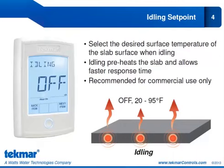In the set temp menu, you will enter the desired surface temperature of the slab when idling. Now we have quite the range here. You can turn idling off, which is actually the default position, or you can configure the idling set point to be somewhere between 20 and 95 degrees. Typically, an idling set point would be mid-20s. It could be high 20s in critical safety areas.